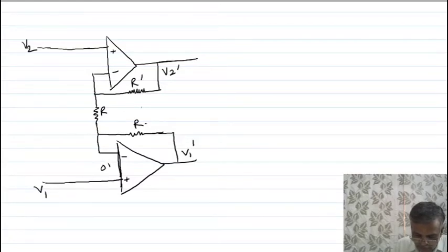Due to very high differential input impedance, this voltage drop tends to 0. Okay, now after this is your buffer, these two circuits are buffers, or you can say voltage followers, and this is connected to your basic differential amplifier circuit.